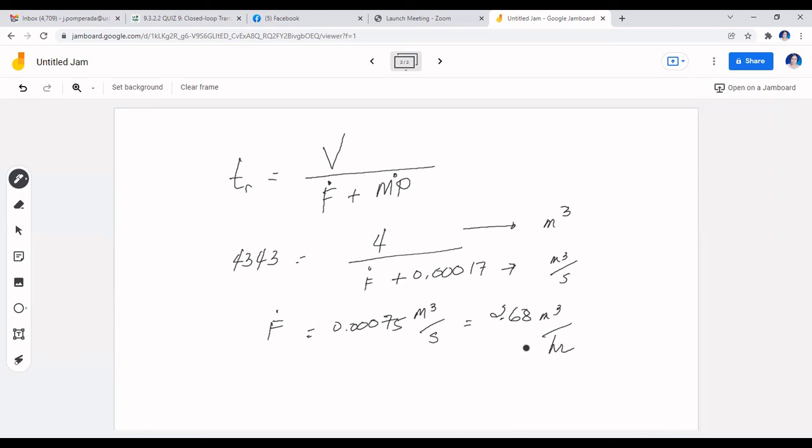as the clear liquor flow rate that is processed by your crystallizer together with the remaining suspension of the crystals that need to grow, because we only dispense the 90% that has grown to that particular size of 100 micrometer or more, meaning the remaining 10%. There is always a remaining 10% inside your crystallizer. So this now ends the fifth sample problem, our last sample problem under industrial crystallization.